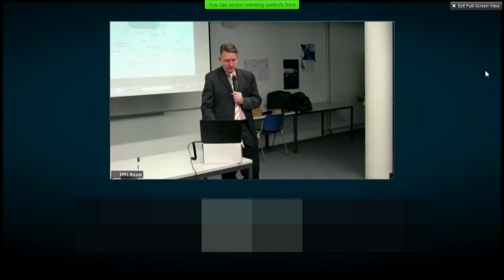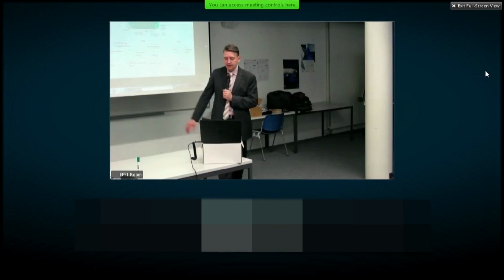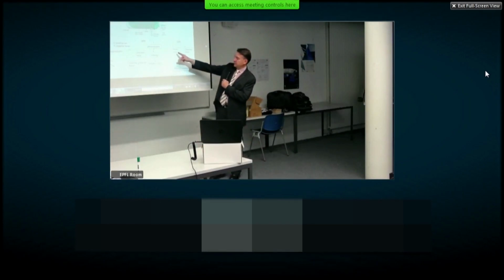Here's an example from xerography. We have our photoreceptor belt. We have residual toner on the photoreceptor that needs to be removed. We do this through a cleaning lamp and then a blade. In this case, you can show this as an OPM, and you can show it here, where the residual toner is transferred from photoreceptor 1 to the cleaning blade 2, and this is shown in the DSM as a mass flow from 1 to 2.